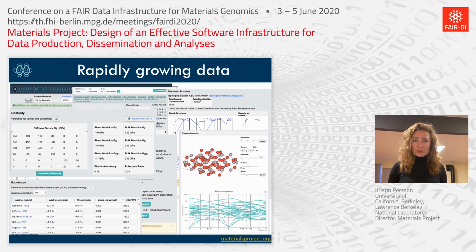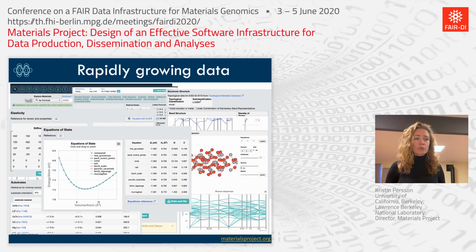And we have substrates. So if you want to try to make a particular polymorph of aluminum oxide, these are the substrates, among all the available substrates that are common in epitaxial growth, that would promote a particular polymorph in terms of the topological match with the candidate polymorph, as well as the elastic strain. So a minimal amount of strain and a good topological match. We also have equations of state for a small subset of materials. Hopefully more is coming, all depending on computational availability.